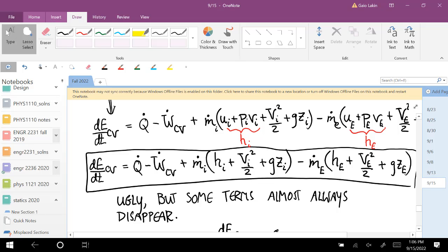If you need a very rough answer, then you probably can ignore the heat transfer, except in extreme cases. If you need a very precise answer, then even if it's moving through pretty quickly, even if the thing is insulated, you have to take it into account. So the main worth of having that in mind is that if a problem says it moves through fast, it's telling you that you can cancel that term. Okay.